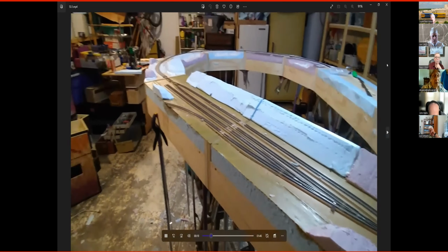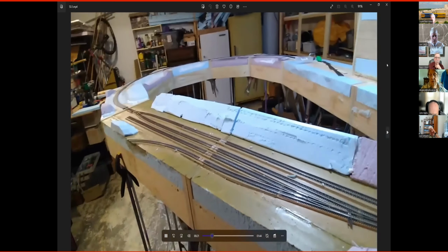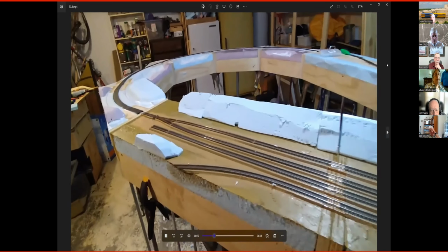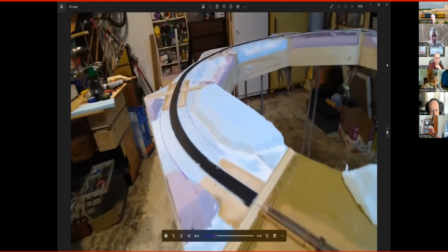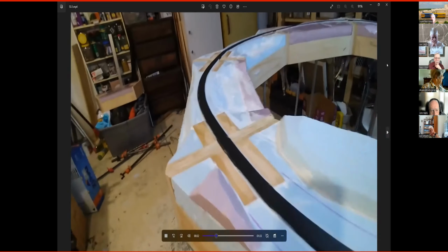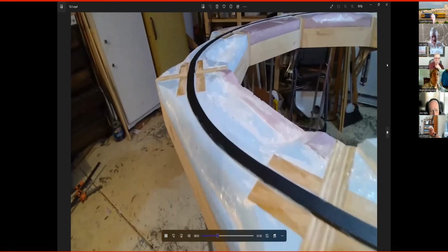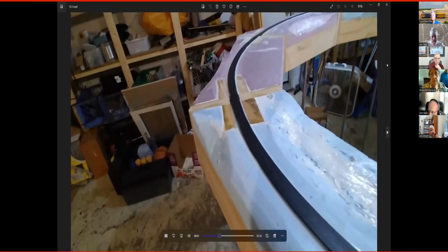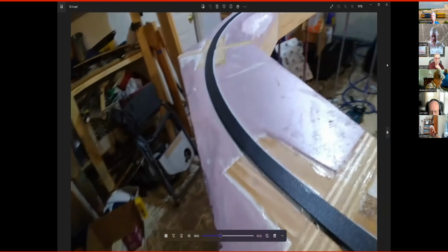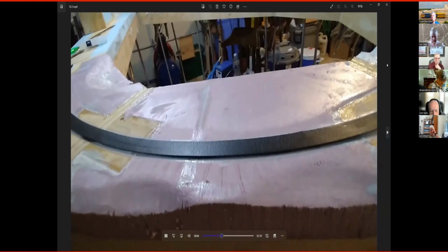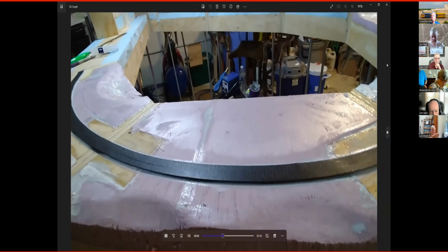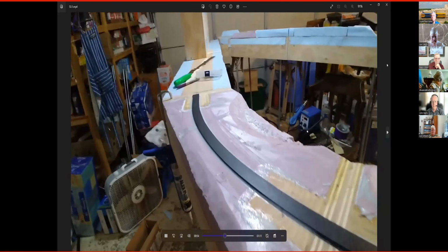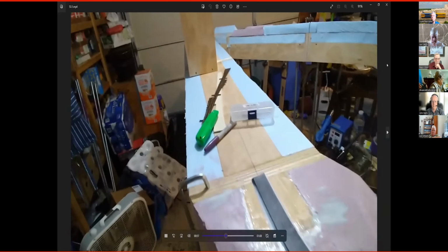We went out the other day and took photographs and found that this section of track, although it isn't a yard out there, is in a cut the whole way, and the cut's about 14 feet deep. And it continues around this first corner, and then it goes into a fill situation. So we've got 2 modules here that do have fills on them. And then the 4th corner has a road that'll come across probably right about there that accesses the main 3-track yard. Then this last corner is on a cut again, and that brings us around to the yard.